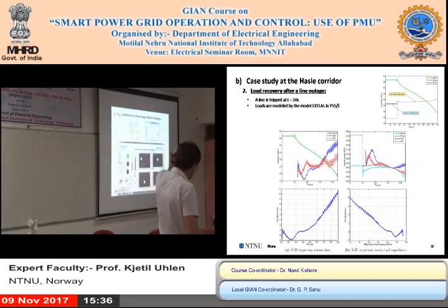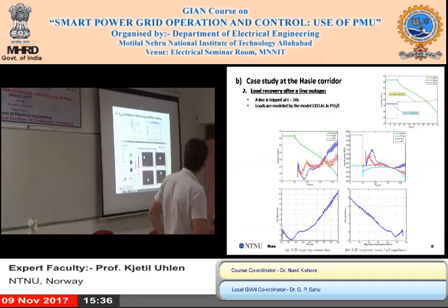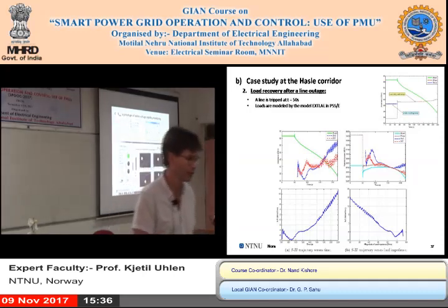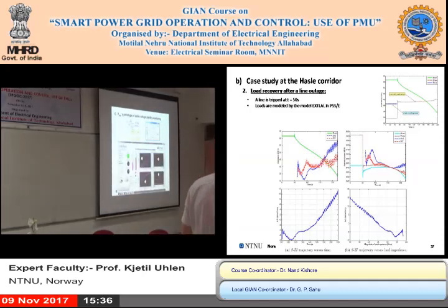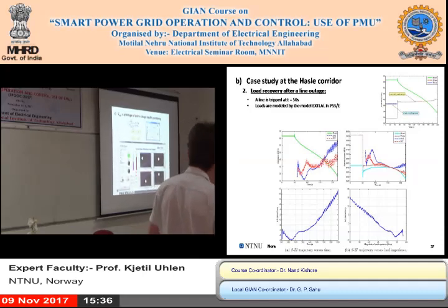So to sum this up, this is implemented in a prototype, also the same as here, implemented in LabVIEW software, and it runs not on this computer, but because it's connected to the PMUs in the high voltage transmission grid in Norway.